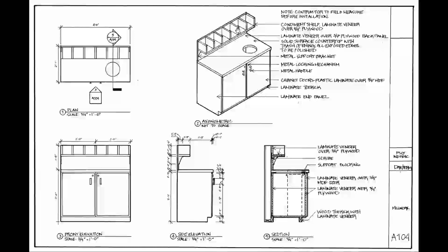Now, when you're tracing this, I would recommend, instead of going from profile line down or thinner, I would probably start with the thinnest line weight and then move up, because as you get here to these edges and the hardware here and these itty bitty little circles and even these lines here, a 0.3 millimeter drafting pen, it's going to smudge.